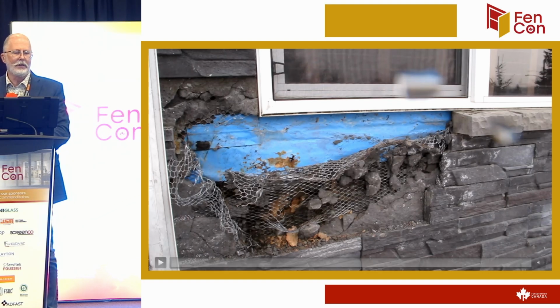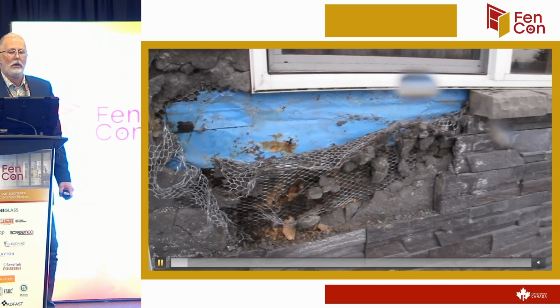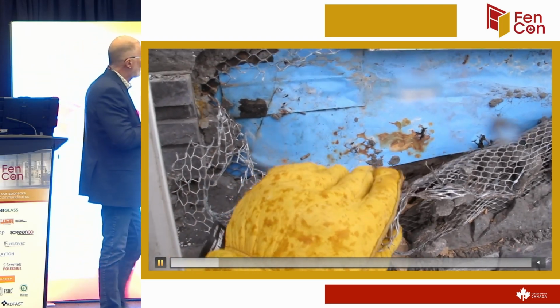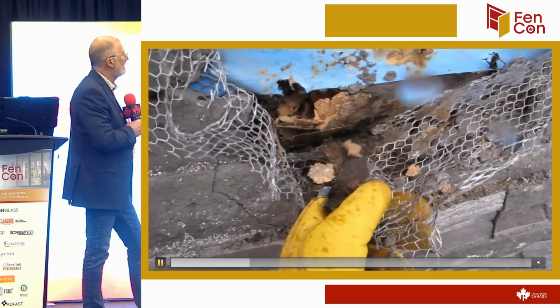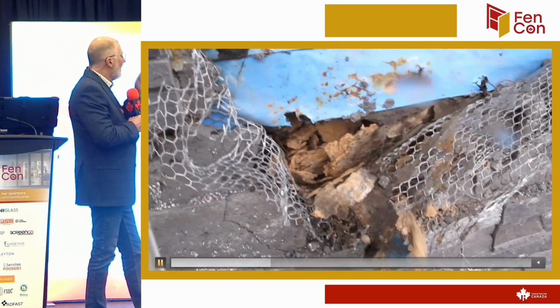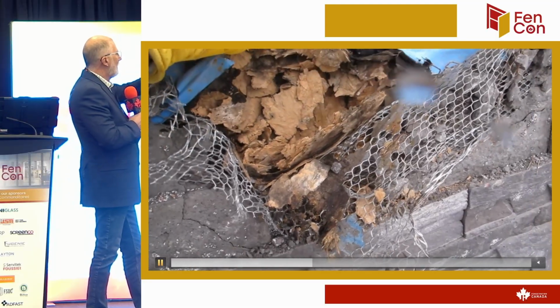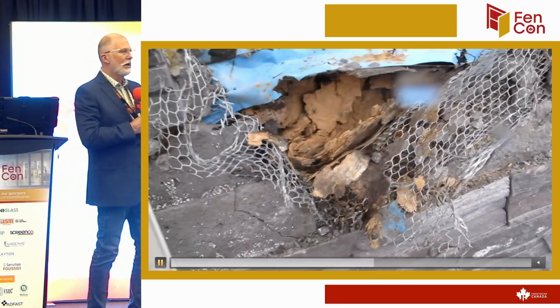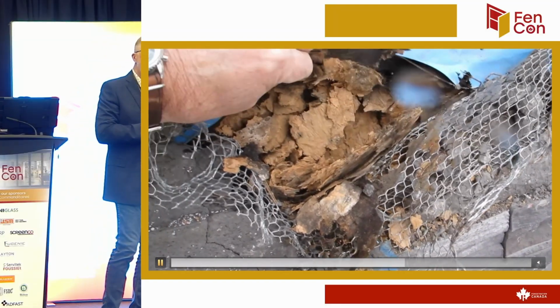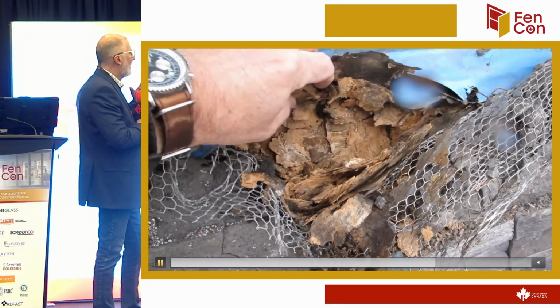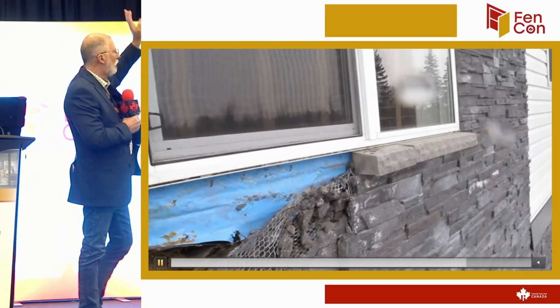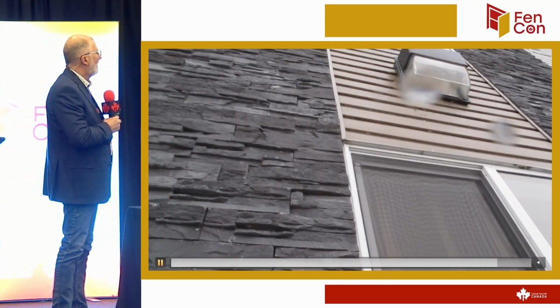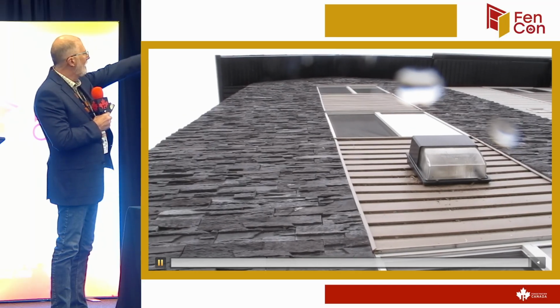Now, this is an example of a 4-side sealed window. If you look at this, this is a 7-year-old apartment in Red Deer, Alberta. They've put blue skin all the way around, but the OSB is completely destroyed. Everything was draining into that opening, but nothing was allowed to drain out. So it completely destroyed an entire wall, 4-story apartment building, all the way up in behind there.